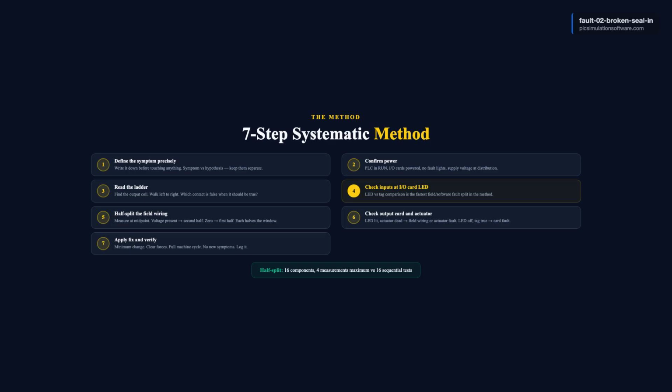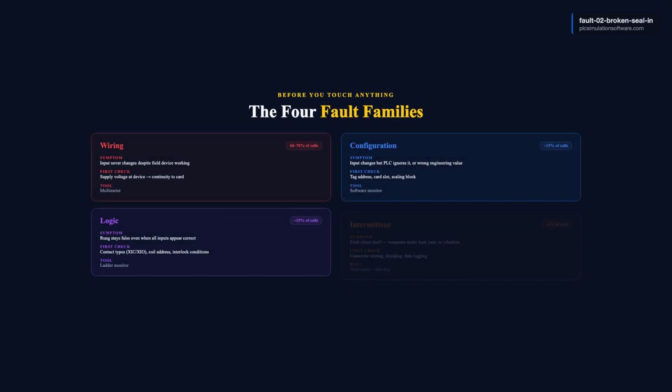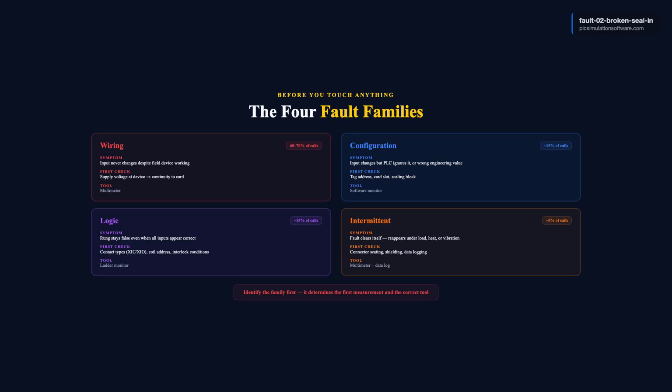Before any diagnosis, identify which fault family you are in. This determines your first measurement and the correct tool. Family 1. Wiring faults. 60 to 70% of field calls. Broken wires, open circuits, transposed terminals, corroded connections.